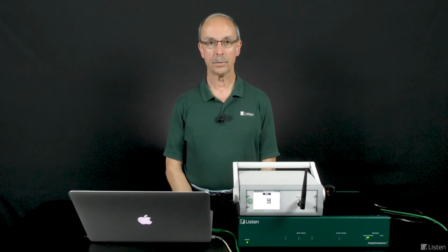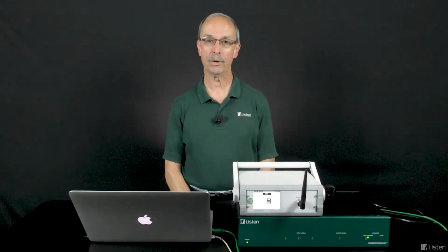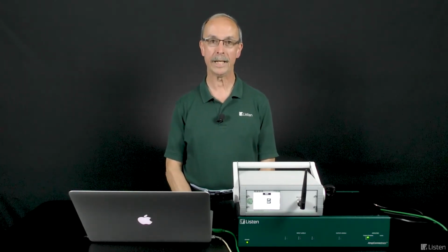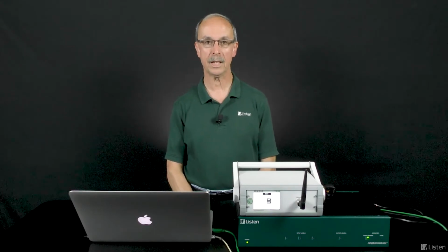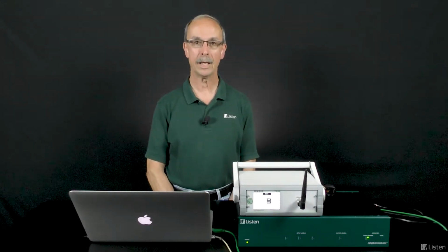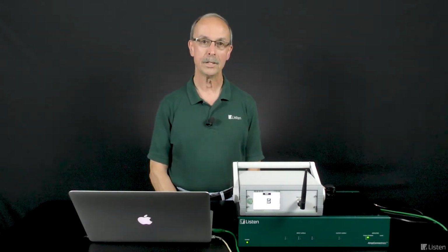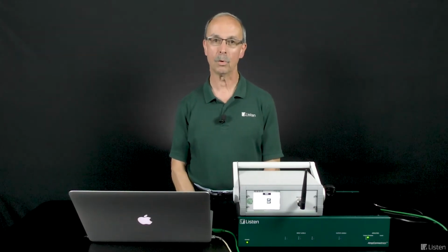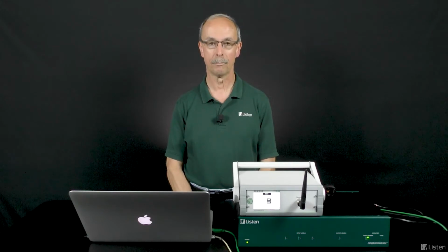Unlike Bluetooth dongles, which are essentially black boxes having unknown characteristics, the BTC4149 is a laboratory-grade Bluetooth 3.0 compliant RF interface. It supports a comprehensive suite of codecs, protocols, and other significant settings and can be configured through touchscreen controls, a command line interface, or message steps in a SoundCheck sequence. These options provide unparalleled control over protocol selection, pairing options, and transmission power.